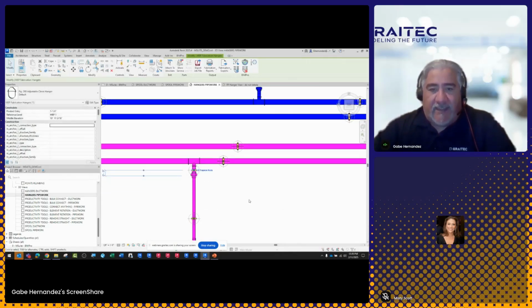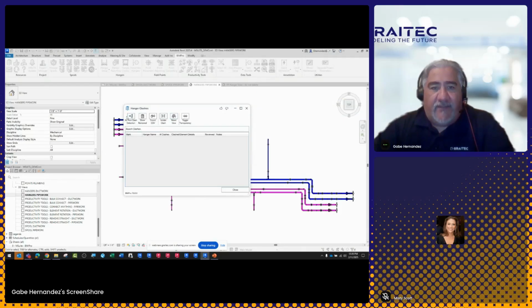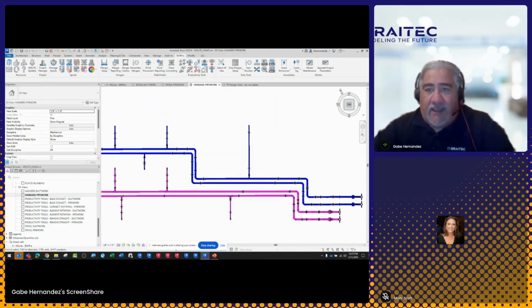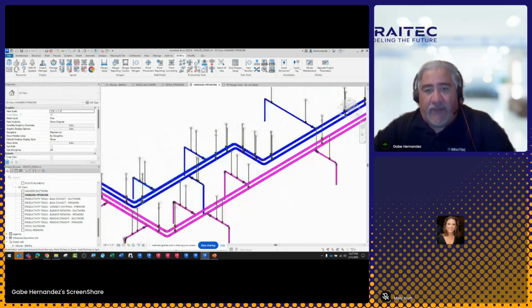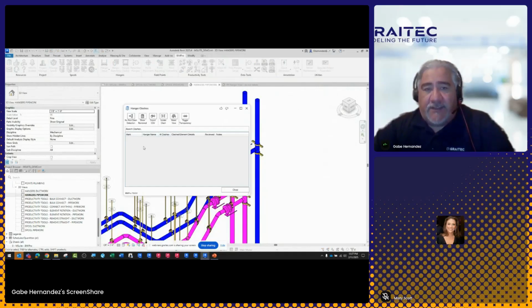I'm going to go ahead and disconnect it anyway just to see if I can get this to work. Rerun clash. No, I can't. Reset view. Rerun clash. Well, that's good anyway that it's not clashing with others. That one's been disconnected. But you'll get clashes in here. And it will find them for you, and it will allow you to isolate clashes, repair them, and you just basically keep running the clash report until it goes away.